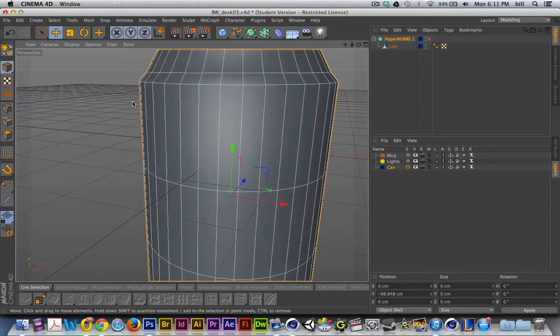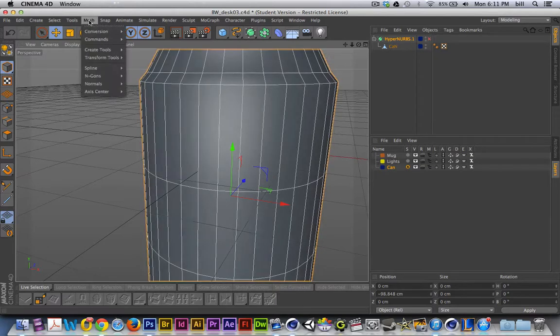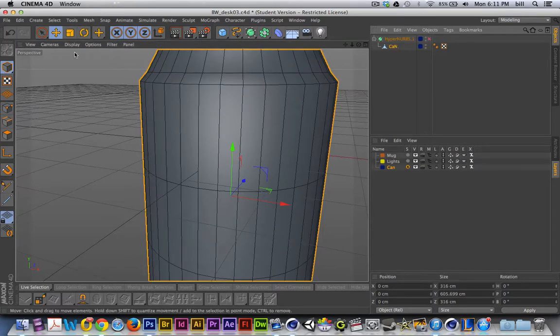And remember, in earlier presentations, I've mentioned that to get a tighter corner or a more articulated angle when it comes to hypernurbs, you've got to have 2 points or 2 edges very close together, or really you need 3 to control that transition. And so what I'm going to do is I'll select the can itself. Got to make sure that the actual model is selected.